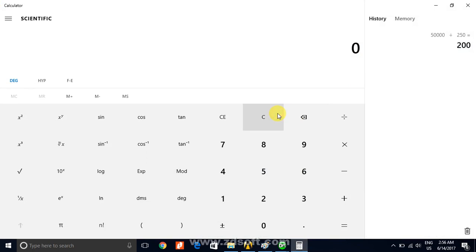So the Young's modulus of elasticity is 2 into 10 to the power 5 multiplied with 1.2 into 10 to the power minus 5, and the powers plus 5 and minus 5 will cancel out, and 2 into 1.2 into 200 minus 22. It's 178, I think you can do that one. 200 minus 22. If you multiply all these things, you will get 427.2. This is the thermal stress.